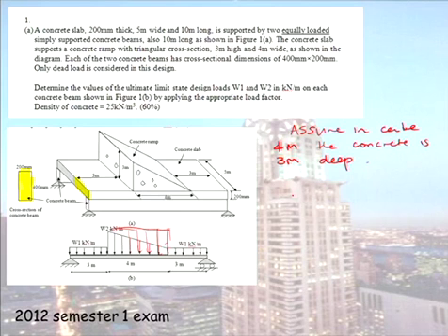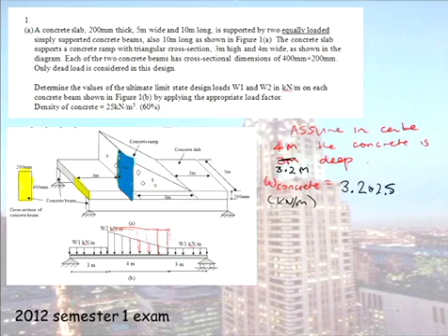So thus when I work out now the weight of the concrete, I base it on cross-sectional area, plus my W1 value. So how about I take it all the way down here? When I'm saying it's assuming it's 3 metres deep, it's not actually 3 metres deep. Can you see there? It's actually 3.2 metres deep throughout. So the weight of my concrete here, in terms of kilonewton per metre, is just 3.2 metres deep times 2.5 metres wide times the density of concrete. What did we say our density of concrete was? 25.